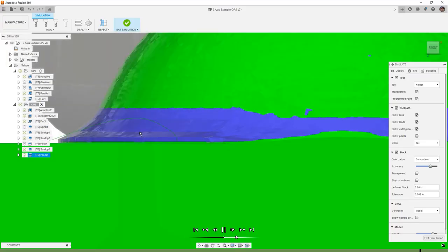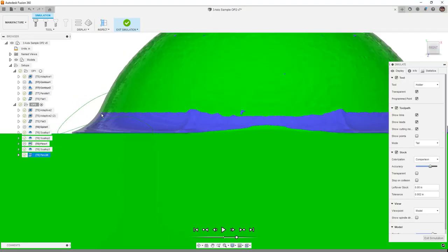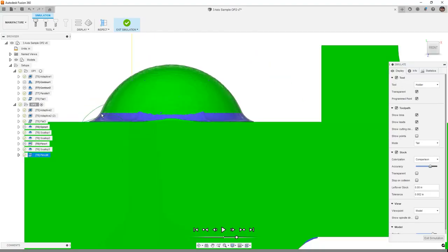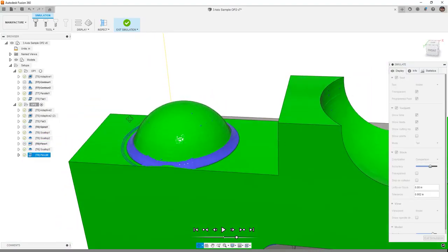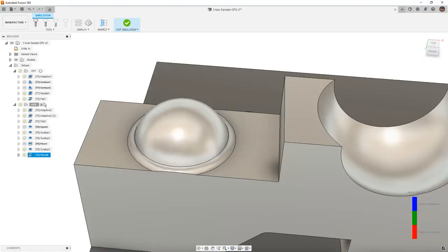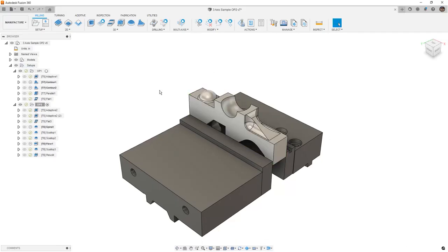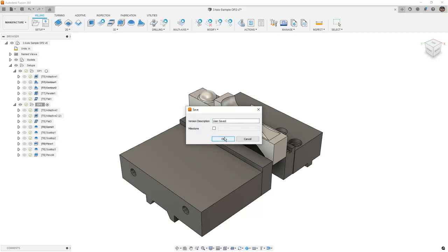This takes a little bit more exploration, and oftentimes these small details are where it's going to be difficult for you to get all the material removed. One of the best options here is likely to use a smaller ball end mill to come back and clean that up. But I want to leave it at this because this is a great area to explore, and I think coming back in a challenge or a practice exercise will help us explore the toolpath a little bit more. At this point, make sure any changes are saved before moving on to the next step.